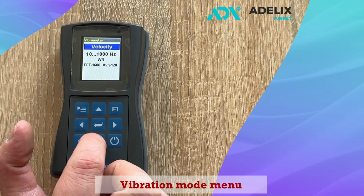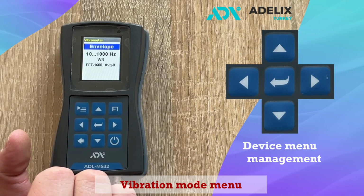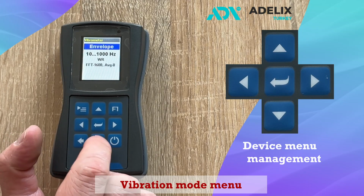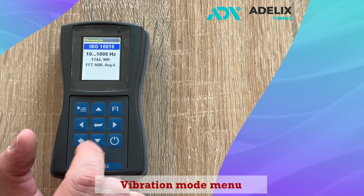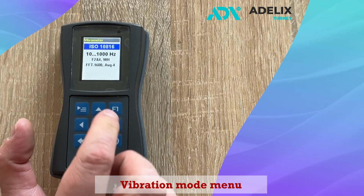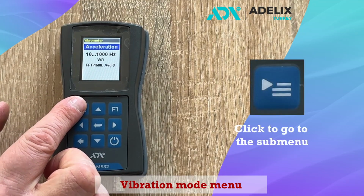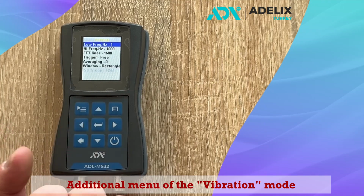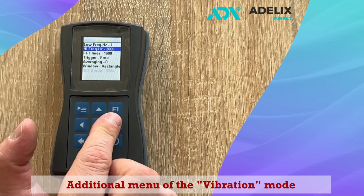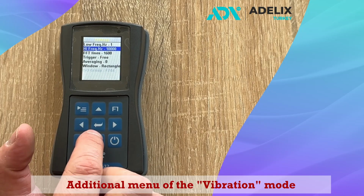On the screen, we see the following modes: vibration, vibration velocity, vibration displacement, envelope analysis diagnostics, alignment to ISO 10816 standards. By pressing the button on the device, we access the menu for configuring the vibration mode. In the mode settings, we can adjust the frequency range from 1 to 10,000 Hz.